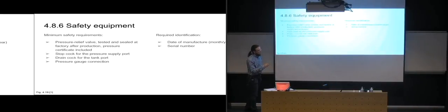That is because hard stamping can be difficult to read, because basically you are just stamping in dots to create letters and numbers. So sometimes they can be difficult to read, but you are hard stamping them into the material so that they are there, because the hard stamping can't disappear. So if you're going to make it disappear, you have to manually go in there and grind it away, and then you know that someone's been doing something they're not supposed to do. While having a more readable sign plate, that one can end up disappearing somehow. But then you still have the hard-stamped serial number and everything on the material behind the plate.